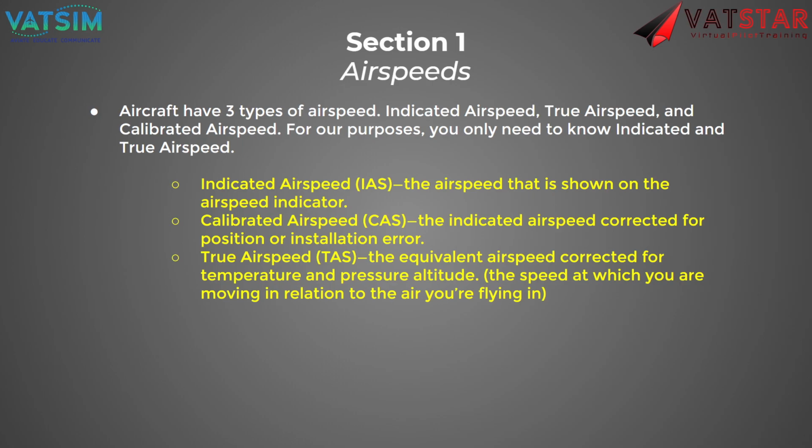I believe it is the indicated airspeed, but corrected for some errors. So close. What you're actually talking about is calibrated airspeed, and I have that up there. Calibrated airspeed is corrected for errors. Now you are correct, you can get true airspeed from indicated airspeed.